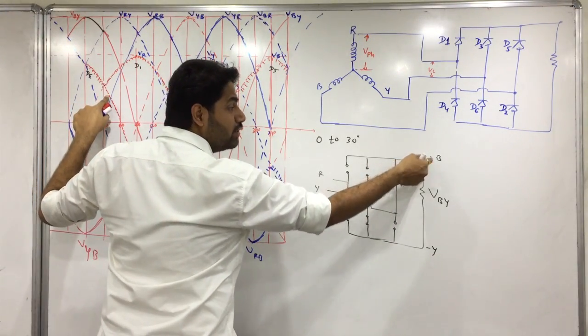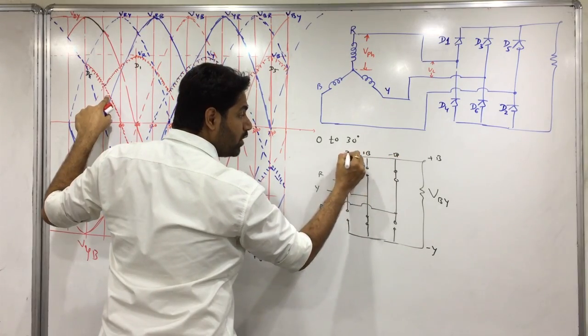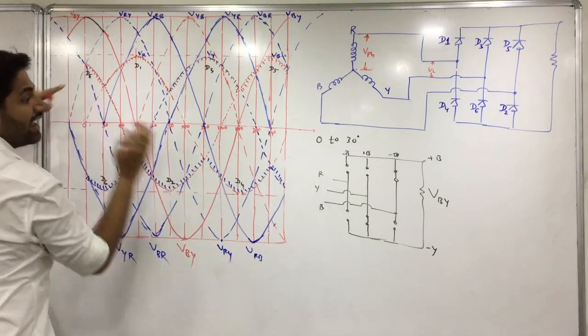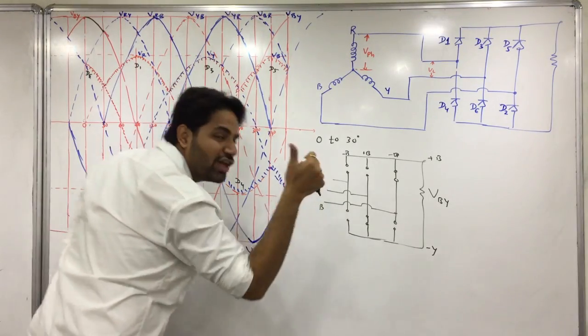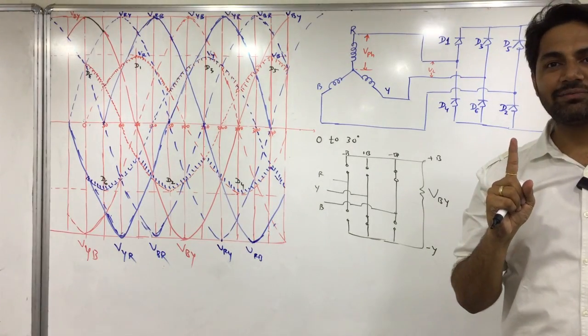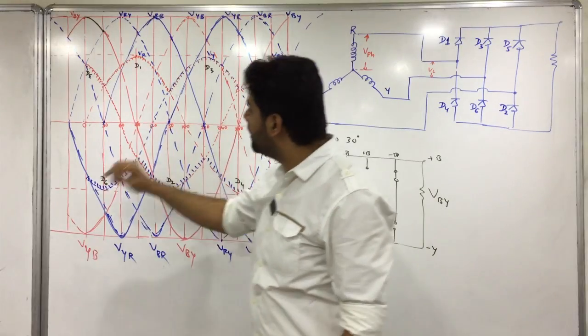So voltage over here will reduce, because right now plus B is coming over here. So here plus B is there, meaning voltage is bigger and here R voltage is lower. So this diode cannot conduct. Everyone understood why that diode is not conducting?